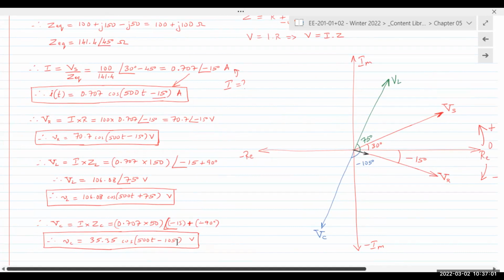So the next circuit, while you're thinking about this, is very similar. Again, it uses R, L, and C, but you are now asked to find the power for every component. So we'll solve for the voltage and current in the circuit. That's an example again of AC analysis, and then we'll solve for the power. Any questions about any of this? So again, two ways to solve. You apply Ohm's law twice, or you apply voltage division. Multiple tools in your toolbox. It's up to you which tools you wish to use.